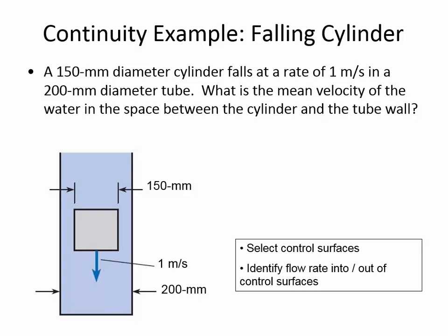But then when we put on the 90-degree, hold on, there's two of these pieces. There's supposed to be a flat one. I must have, we've got two different sets. I didn't bring in the 90-degree deflector. But the 90-degree deflector, essentially, it screws on to the cylinder here, and the flow comes up, and it just sort of spreads it out sideways. It causes the flow to change directions from completely vertical to completely horizontal. And it's generating much more of a force.